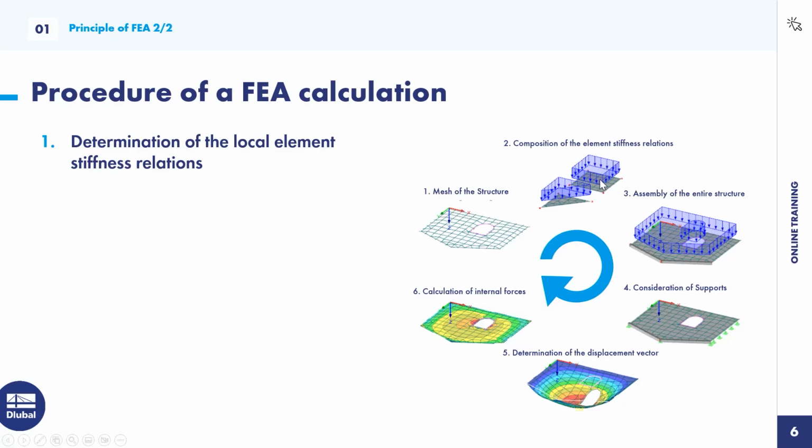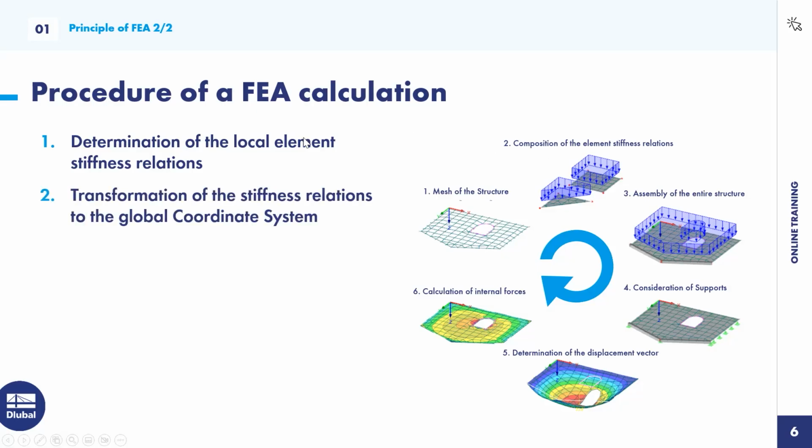So we have the system, if we only inspect one finite element, already known. And in the next step, we will combine all of those elements, and therefore we will combine the element stiffness matrices and the element load vectors into the global stiffness matrix as well as the global load vector.